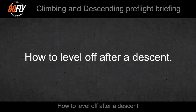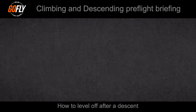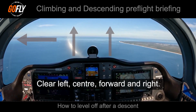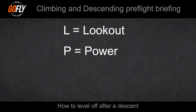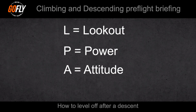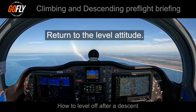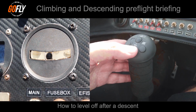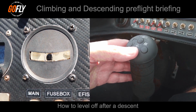We will now demonstrate how to level off after a descent. When it comes to leveling off after a descent, the acronym is LPAT. L is for lookout for other aircraft. We clear our left, center and forward and right. P is for power. Increase the power back to the cruise power setting. A is for attitude. Return to the level attitude. T is for trim. Once the airspeed has stabilized, we trim the aircraft and also make sure the aircraft is in balance.